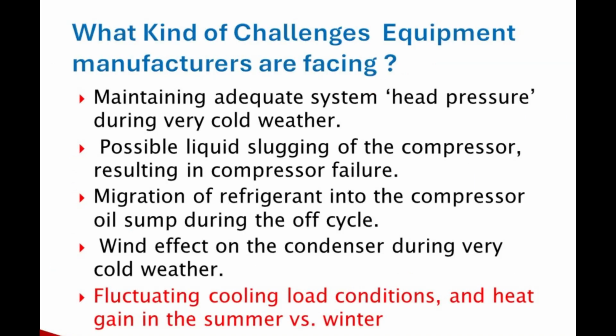5. Managing fluctuating cooling loads. In any room, heat gain and heat loss is different at any given time. Mitsubishi's variable capacity inverter system with an electronic linear expansion valve matches the system's BTU output to the heat gain in the space, providing tighter setpoint control and improved dehumidification. This reduces on-off cycling, extends compressor life, and includes a soft start feature to lessen the stress on the building's electrical supply.